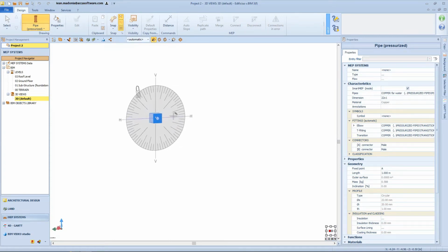The choice of the plane also involves moving the protractor on the selected plane, and the V-axis, the vertical planes, and horizontal H-axis will be present. If you do not want to constrain the pipe to remain on one of the planes identified by the cube, you can ignore its use by clicking on the padlock that appears next to the protractor. Unlocking the padlock makes the directional cube disappear. In this way the pipe is released and is free to be traced in 3D space. In that case, a second click will be enough to directly define the end point of the pipe.